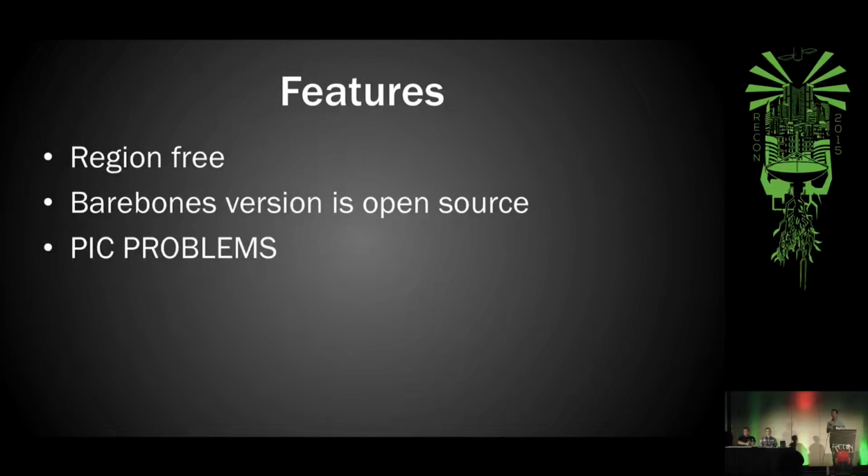I never want to look at that architecture again. Funny thing about PIC, it's pretty terrible. But for this particular microarchitecture, it had some nice features that made implementing this stuff easier than it could have been otherwise. Remember, we mentioned that this is a 4-bit microcontroller. So when you've got things like carry, it all depends on not carry in the 8th bit, it's carry in the 4th bit. PIC actually has a feature called decimal carry. So if the 4th bit carries, there's a flag in the status register. So we were able to implement the code in a pretty straightforward manner, not having to think too hard about 4-bit math versus 8-bit math.